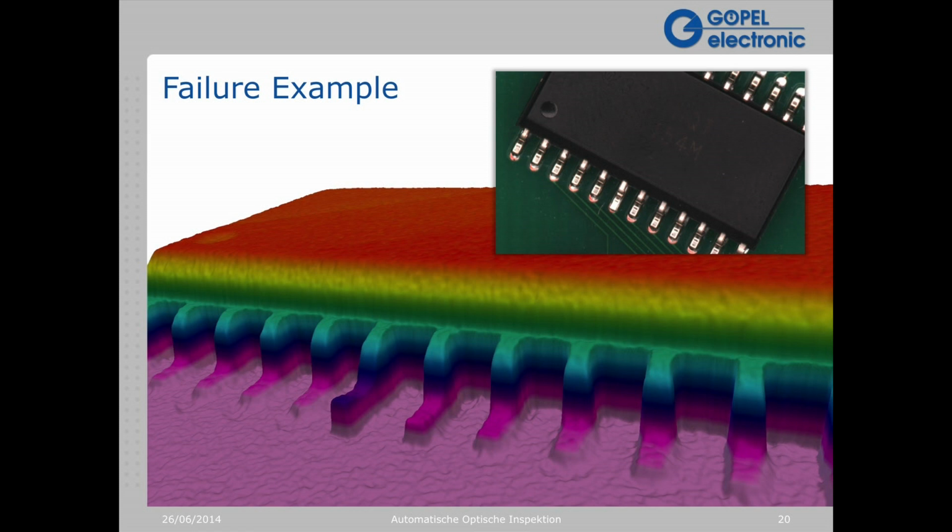However, if we look at the 3D representation, it very quickly becomes clear that this is a lifted lead. We can see very easily that the lead is lifted substantially in comparison to the others. And suddenly the actual nature of this particular failure is made very clear.